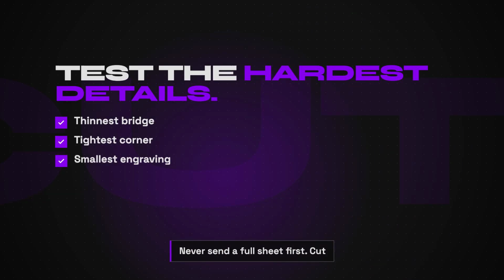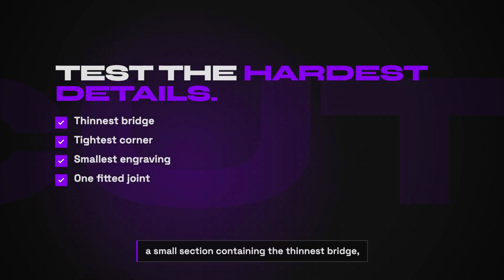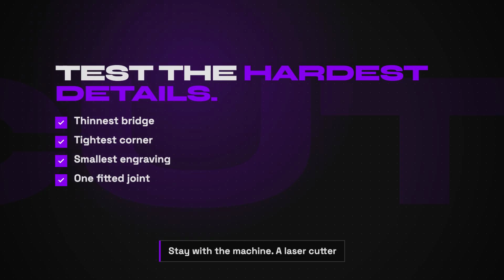Never send a full sheet first. Cut a small section containing the thinnest bridge, tightest corner, smallest engraved detail, and one fitted joint. Confirm scale, focus, origin, operation order, power, speed, ventilation, and fire safety. Stay with the machine. A laser cutter is not an unattended printer.